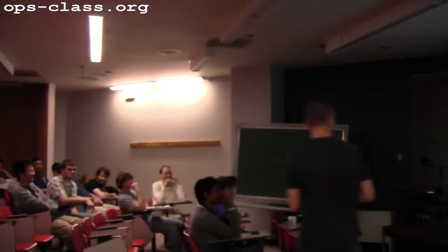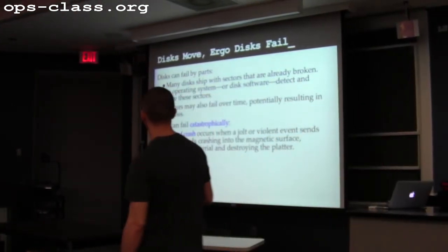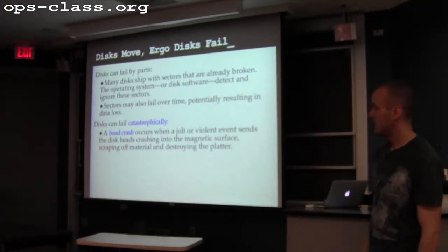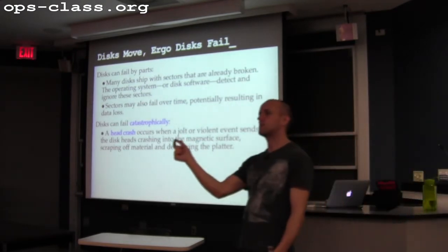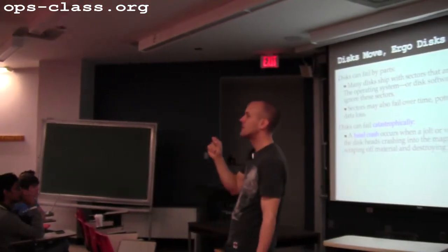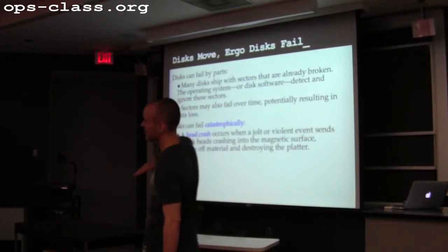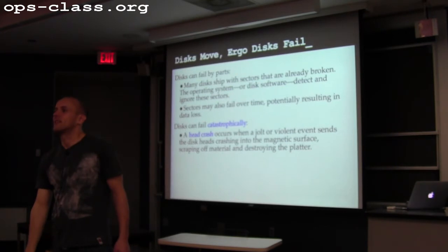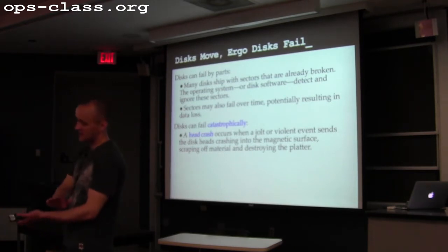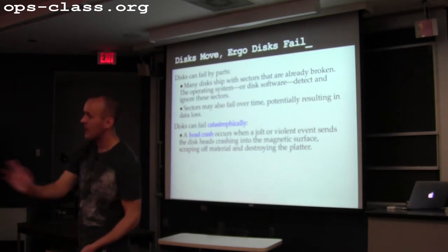Okay, yeah. So I had a laptop when I was in graduate school that went through 6 hard drives in about 6 years, and most of them were caused by me just dropping it or bumping it. Remember, those heads are rotating right above the disk surface while the disk is spinning. If you send an unexpected jolt into the casing, that can cause those heads to essentially dive into the platter, right? And as soon as they start making contact with the platter, given the rotational speed of the disk, they just start tearing off material. And as the disk continues to spin, if the head is moving laterally, it can tear off a whole swath of the disk.